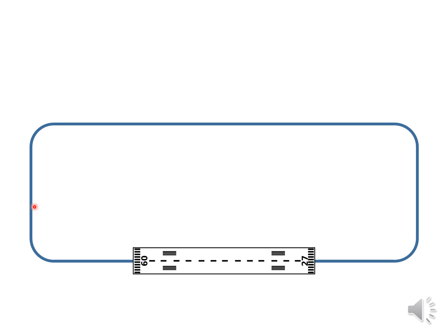In this circuit we can use two patterns, that is a right hand pattern and a left hand pattern. Suppose the aircraft is taking off from runway 09 and after liftoff is airborne, all the turns need to be made to the left, that is called the left hand pattern. And for example, if the aircraft is taking off from runway 27 in this circuit, all the turns need to be made to the right, the right hand pattern. So when the aircraft is taking off from runway 09, it is a left hand pattern, and when taking off from runway 27, it needs to do the right hand pattern.